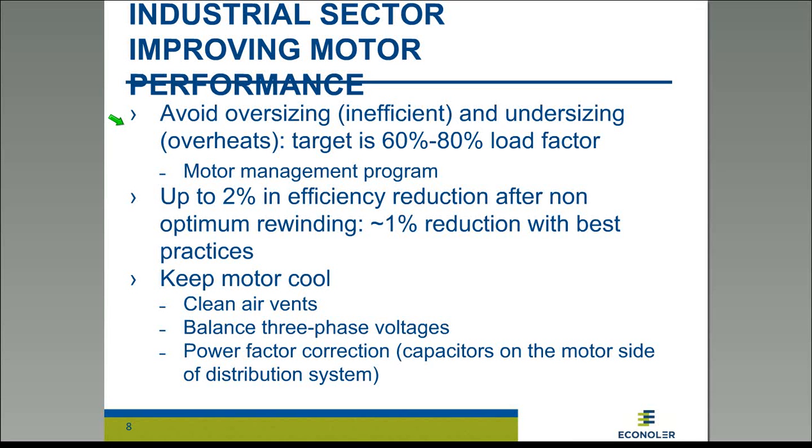Other points that we can mention about motors: there's possibility to reduce energy consumption by avoiding oversizing of motors, so making them run in inefficient zones, or undersizing of motors, which generally results in overheating and shorter life. In several industries, a motor management program has been put in place to ensure that the stock motors, the installed base of motors, are fully optimized, and that's a continuous process, so it's not only a one-time activity.